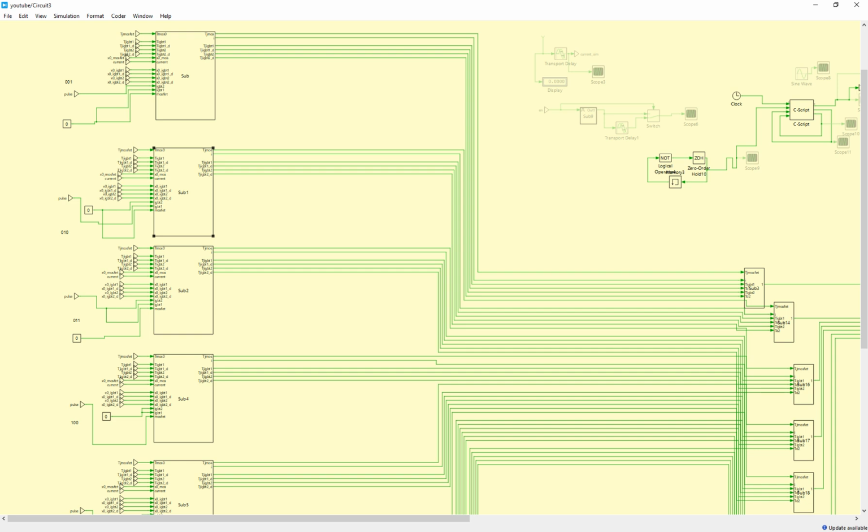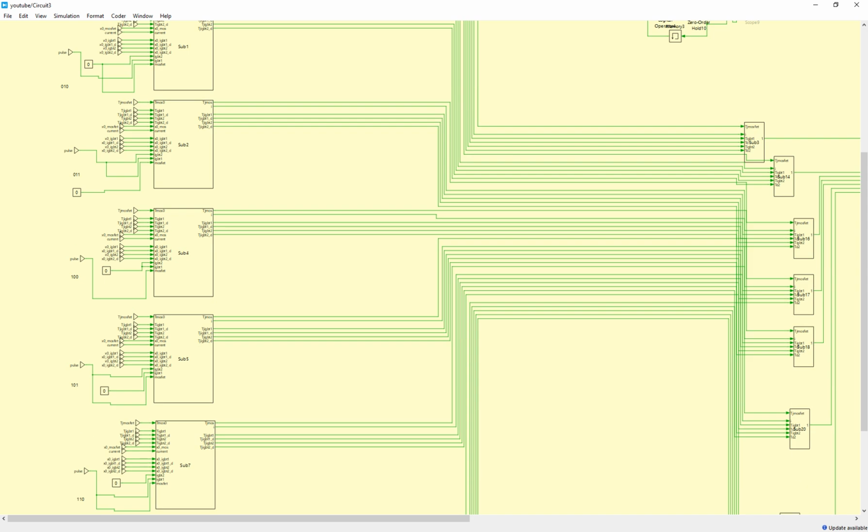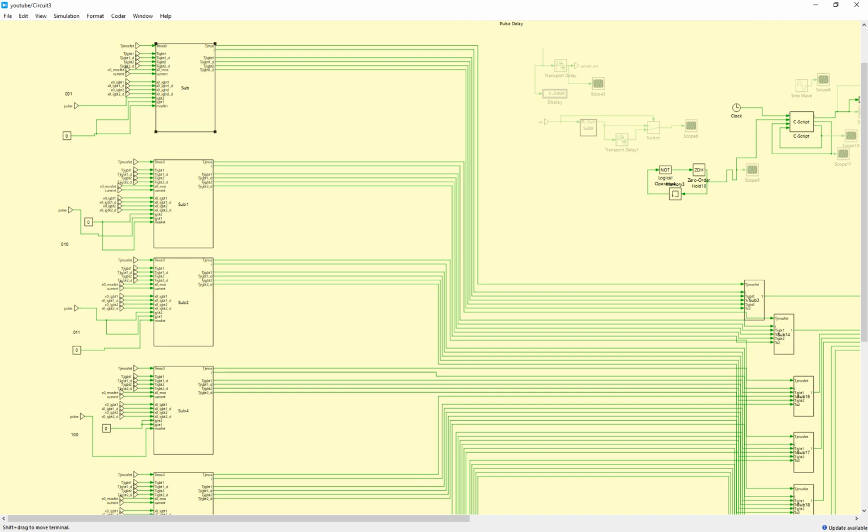That means I need to keep track of the junction temperature for the best one for every switching period. For example, assume you are at switching period number K, you run this simulation and realize that the junction temperatures or power losses for configuration 001 give you the best KPI. Now you need to record the junction temperatures and feed them back to all of these circuits, because they all have to start with the temperature of the previous best solution.